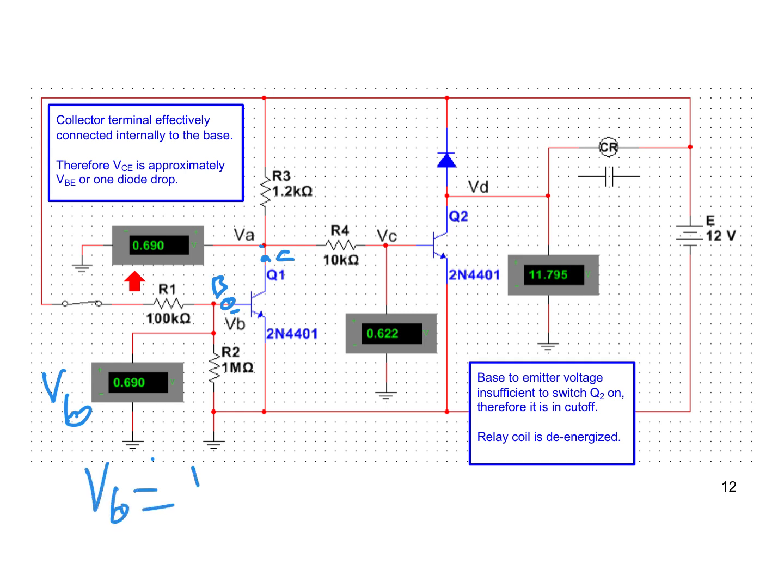equals VA. Because this is exactly the same as that, internally it's shorted between the base and the collector, and because of that, that transistor is faulty.